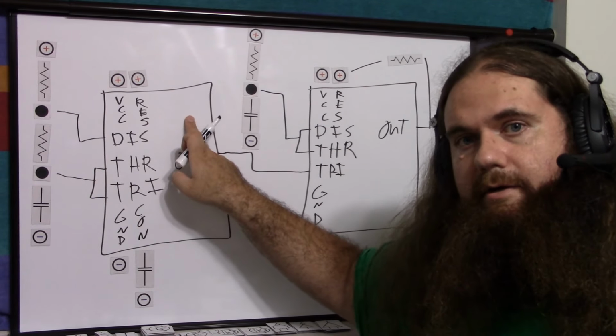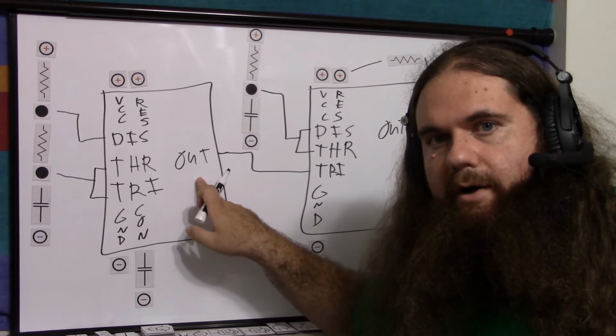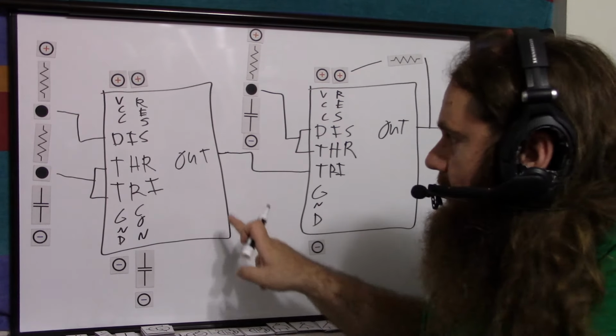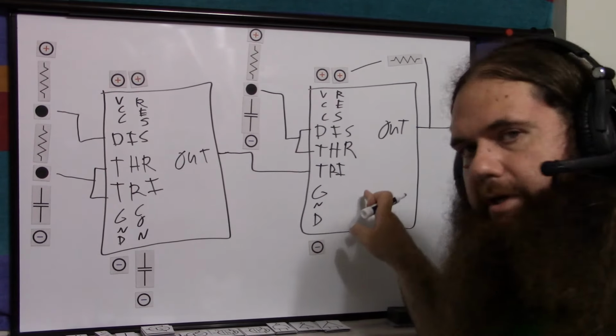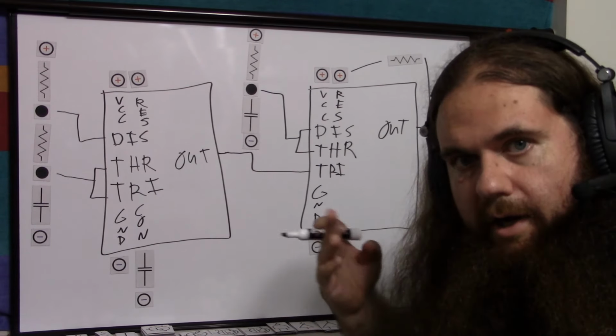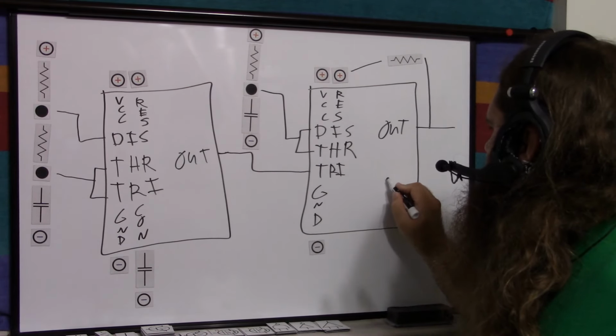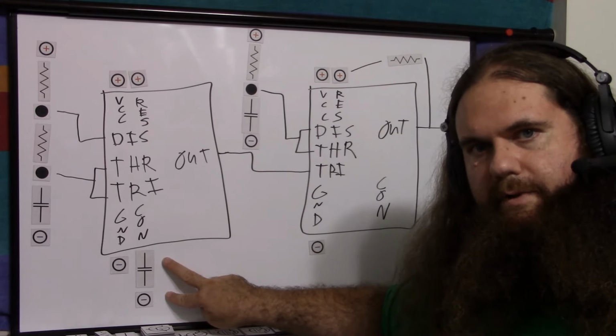I don't need it here because this is the same BJT chip for me. And this is not going to put out the proper high voltage, but it doesn't matter because this is not the output I'll be using. I'm only triggering here. It doesn't matter if it's not the full voltage. So we don't need it there, or I don't need it there. And then we have our cont pin, of course. Now what do we do with that? Normally we just do this again because we don't need it.